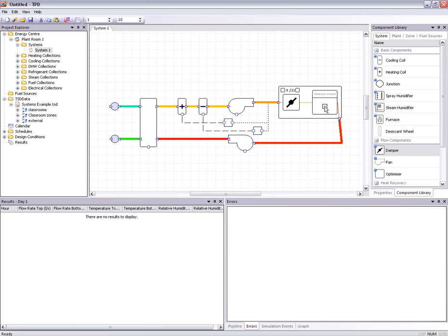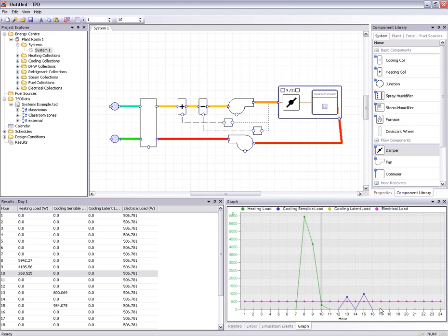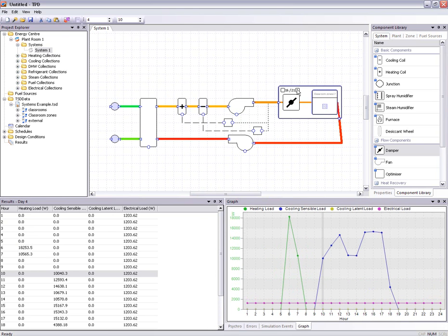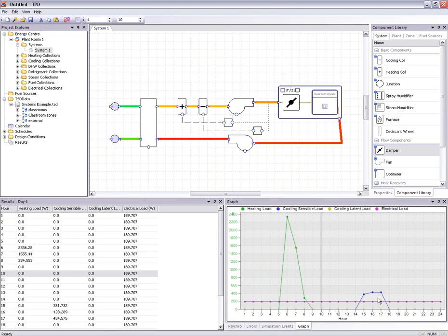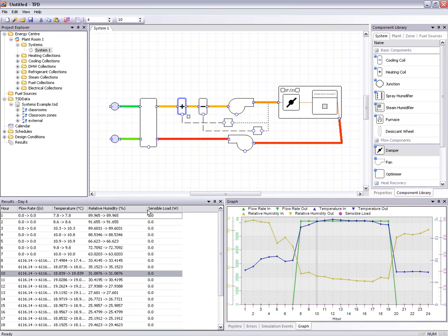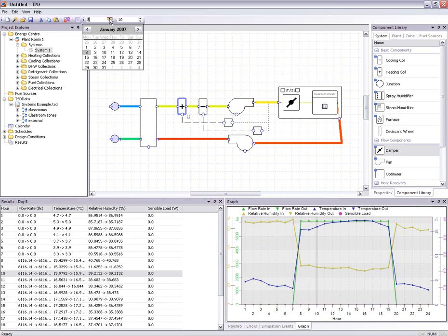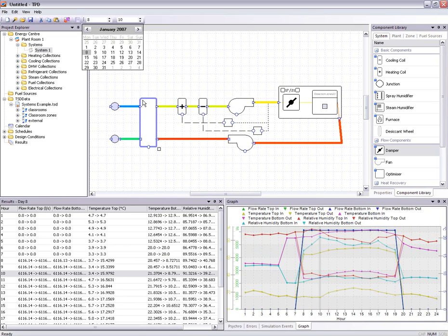Now I can look at the individual fan coil unit for each of the zones and view a graph of the load across the day. You see that the different zones have different loads at the terminal units, but I also have the total sensible load for the heating coil in the AHU. Most of the work in the winter is being done by the sensible heat exchanger.